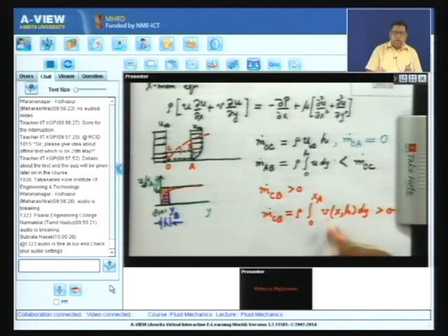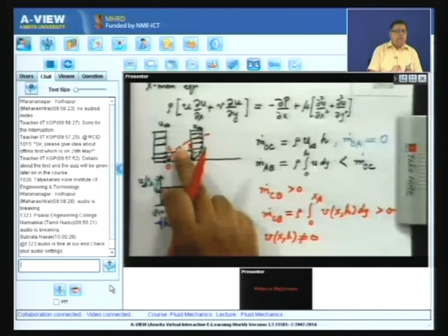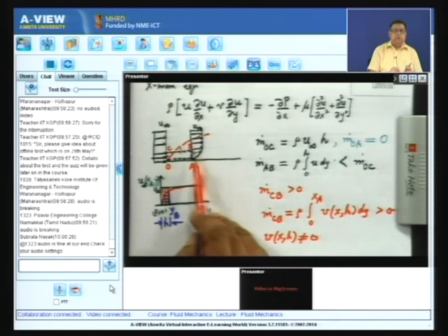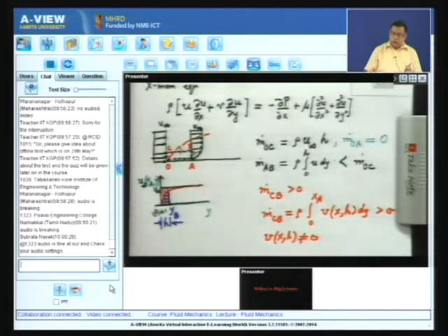So, that can be positive only if the velocity is positive. So, that means that the v at x, h will not be 0 everywhere. In the fully developed duct flows, v of x, y was 0 everywhere. Had v of x, y been 0 everywhere, this mass flow rate would have been 0. Then you would have a contradiction that more mass will be entering the control volume than is leaving. So, that would be a violation of the conservation of mass, and since the density is constant, mass cannot accumulate inside the control volume. So, these are what are called non-parallel flows.